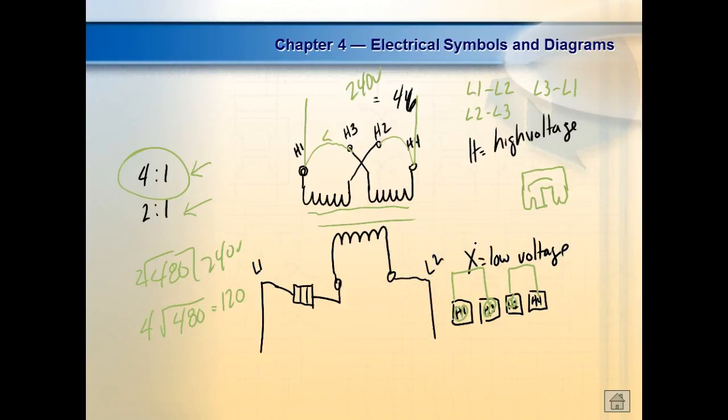We're going to give it a little bit of a name. We're going to call it CL1 and CL2, because what we got up here is an L1 and an L2, and then we're calling this L1 and L2 down there, and they are not the same. One of them's three-phase, one of them's single-phase. Right? You understand? For control line, control L1 and control L2.